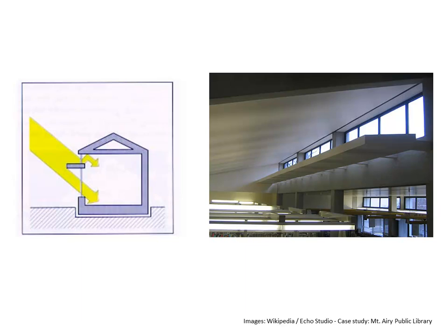The reason why I bring it up parametrically is because in order to study how this works, you could create a diagrammatic light shelf, right? Because light basically works like a laser, it's going to bounce. There are some things you can do in Grasshopper where you could look at the vector. You can change the angle of the vector as it hits a surface to be its opposite, and you can essentially create a parametric version of that diagram to study where your light shelf needs to be.